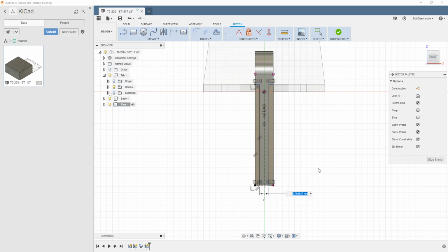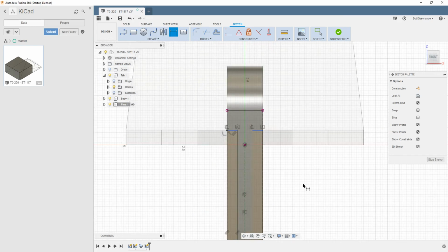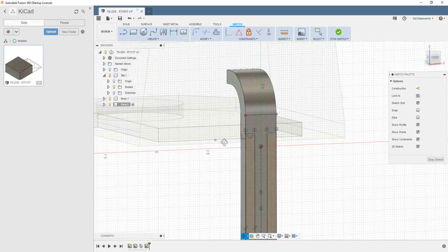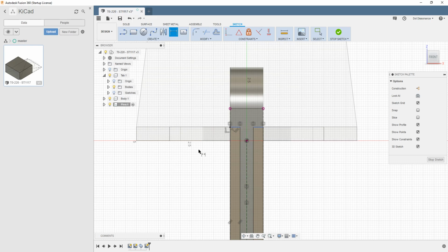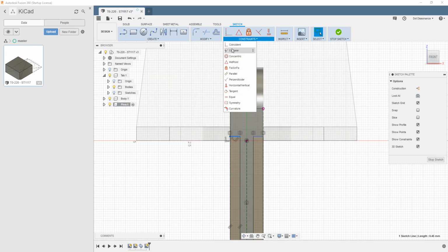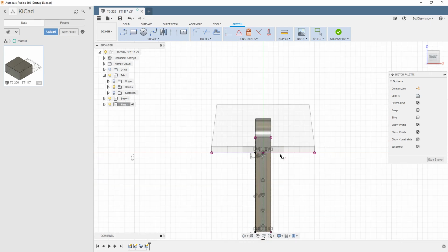So the pin, let's say 0.6. That seems like a pin. I won't even check the data sheet for that. That just looks okay. Now these here, do you want them to be flat? Are they just chopped flat? Or are they square? How do you want them to be? I don't completely care right now, but I don't want this any lower than the bottom of the device here. So you could even grab this and make it collinear with that. And then that's kind of like the perfect fit. The fat, thick end here bends over, hits right down at the base of the PCB, and this goes on through and you solder to the other side.